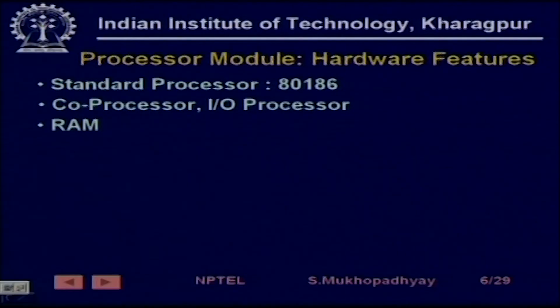You obviously have RAM, which is required for running it. Sometimes you have dual ported RAM. Dual ported RAM is RAM which has 2 ports simultaneously, so it can be simultaneously written into and read from. Okay. This is important, especially when you want to read data from devices which are working without really stopping the device operation. You want to read data or you want to write data. So, you can on the fly parameterize, dump some new parameters for a PLC while the PLC is working.